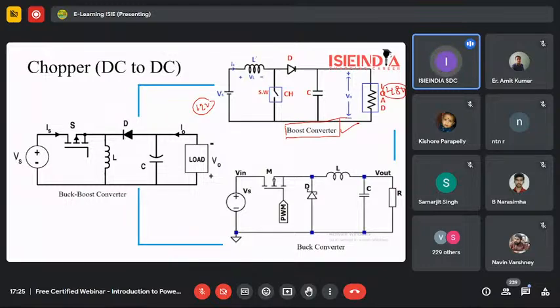So depending upon the switching sequence, like we connect the circuit according to this, L, S and D. So this is inductor, switch and diode. We are getting the boost converter, where the input voltage will be lower as compared to the output voltage.